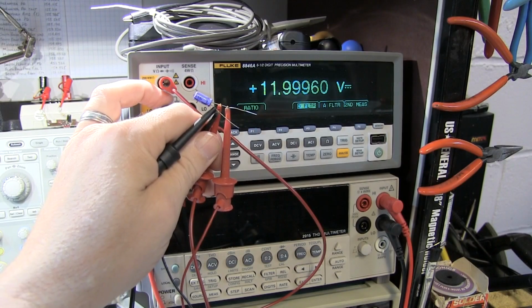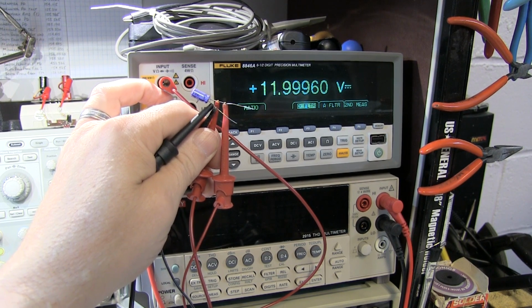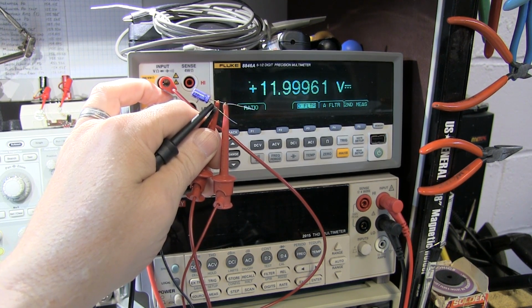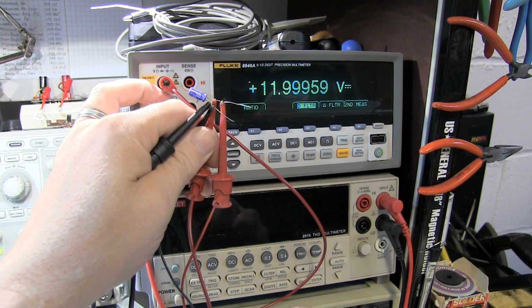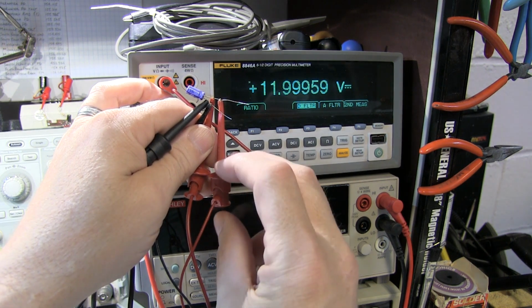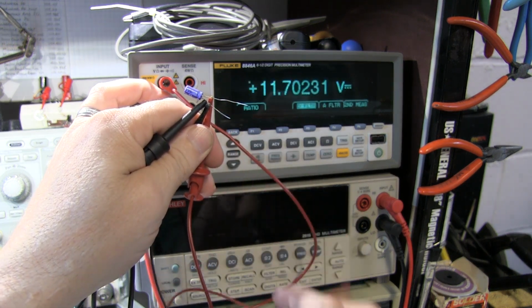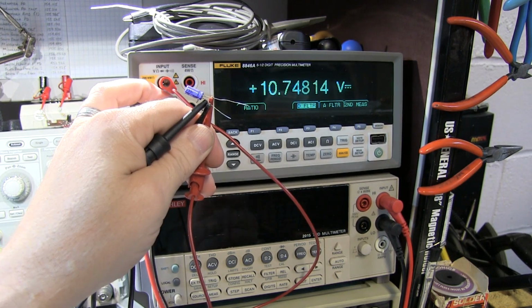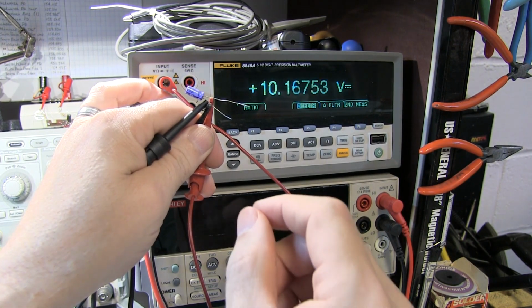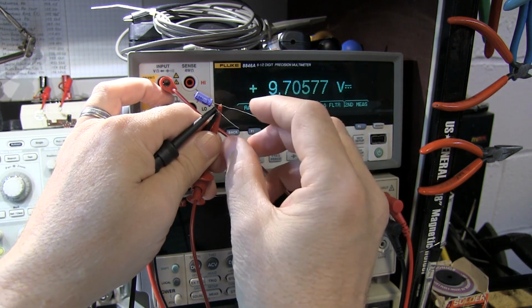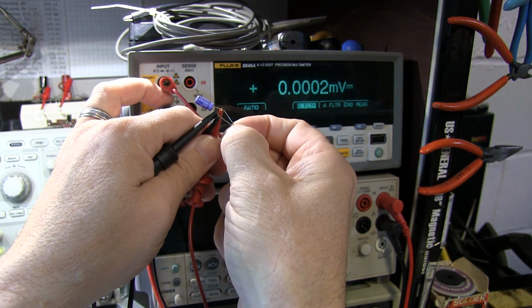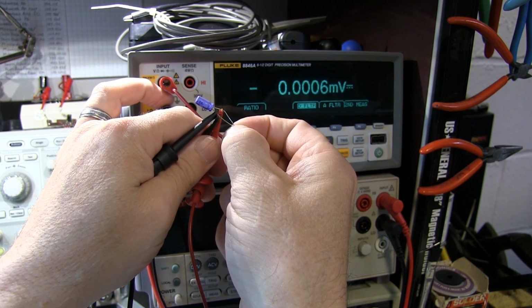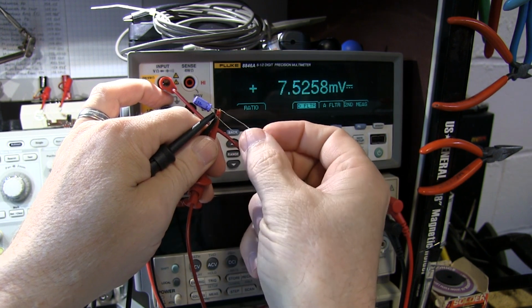So here's just a little 1 microfarad electrolytic capacitor that I've charged up to just about 12 volts. You can see on the voltmeter there, it's just about exactly 12 volts. Now if I pull the power supply off of this, you can see the voltage is starting to drop. It's just leakage and some current that's going into the meter. But let's short these leads out here. So I short the leads out, we can see we've dropped down now to 200 microvolts. But watch what happens when I remove the short.